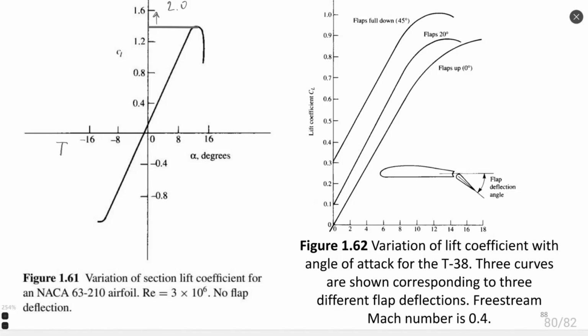Okay, it has some disadvantages which we will not discuss today, mostly related to other aerodynamic parameters, because lift is not the only definitive criteria. You must always see the ratio of CL by CD, and it should go to possible maximum, right? And not just this, there are others.